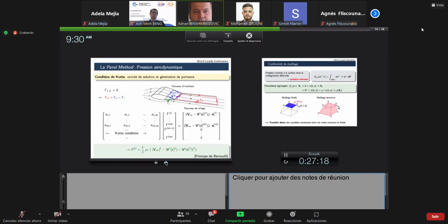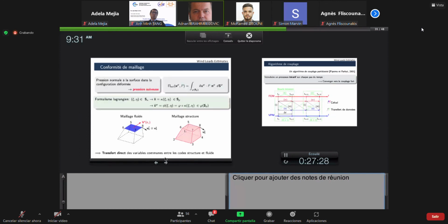So this is actually a fluid computation which is kind of boundary element, because the only thing that you're presenting is the fluid structure interface and nothing else. All the rest is solved analytically. And so this is adapted by using it into the solid model of your wind turbine blade, where the exposed facet of a solid element that is exposed to fluid is used for this type of computation.